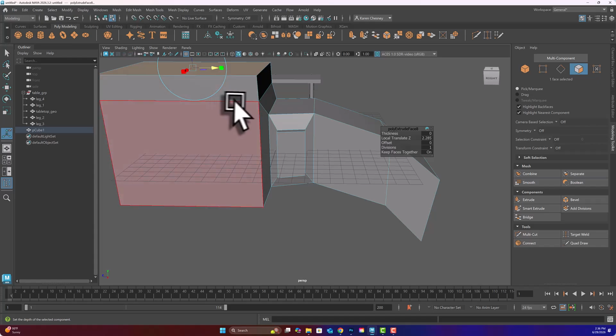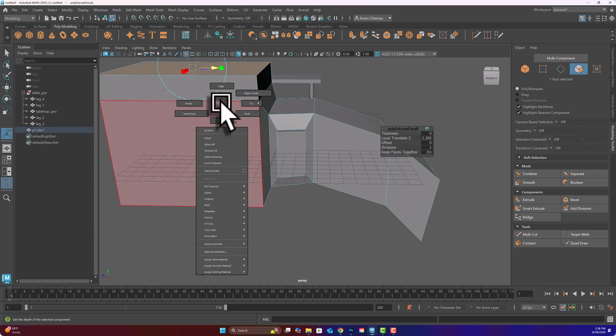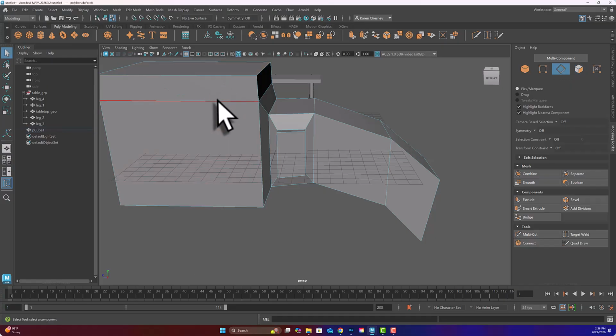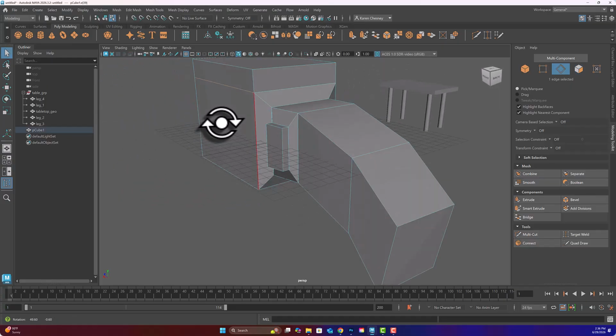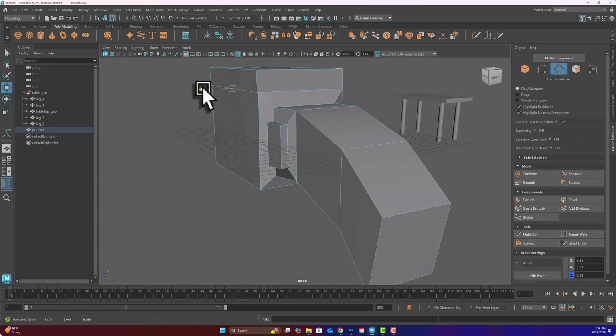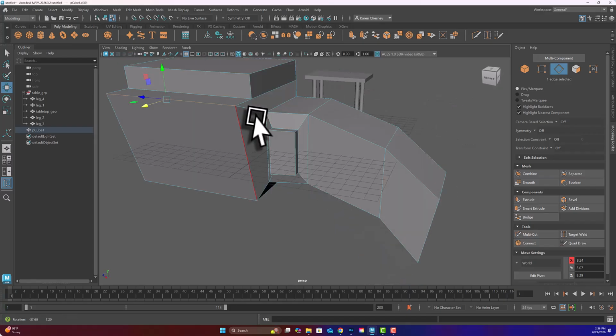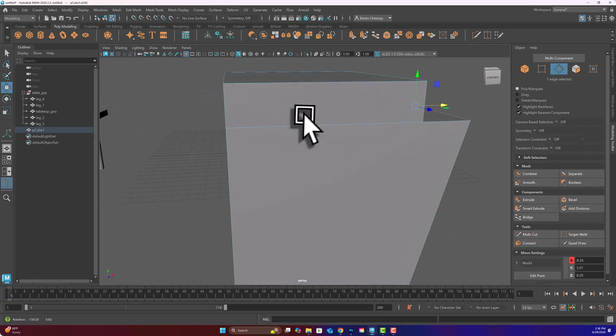But remember, there's another face in there that I didn't change. So if I go to do something to, say, this edge, it should be broken. See how it should be pushing that face in together, but it's acting like it's a separate piece there. It's almost impossible to fix a double extrusion unless you catch it really quickly.